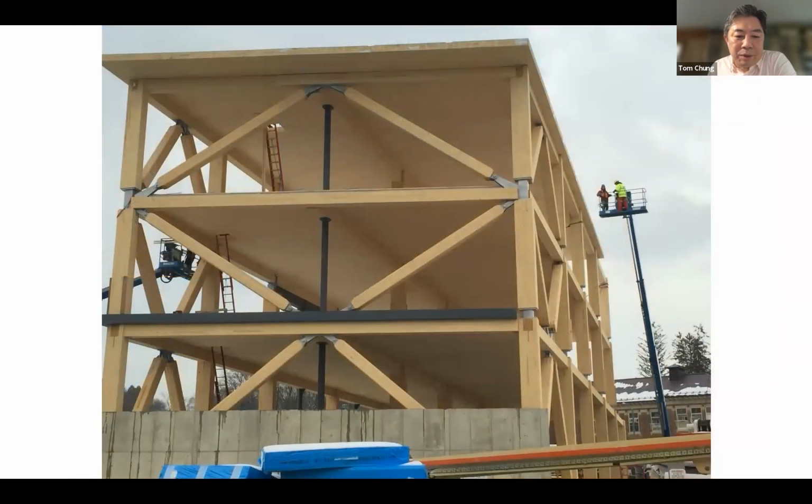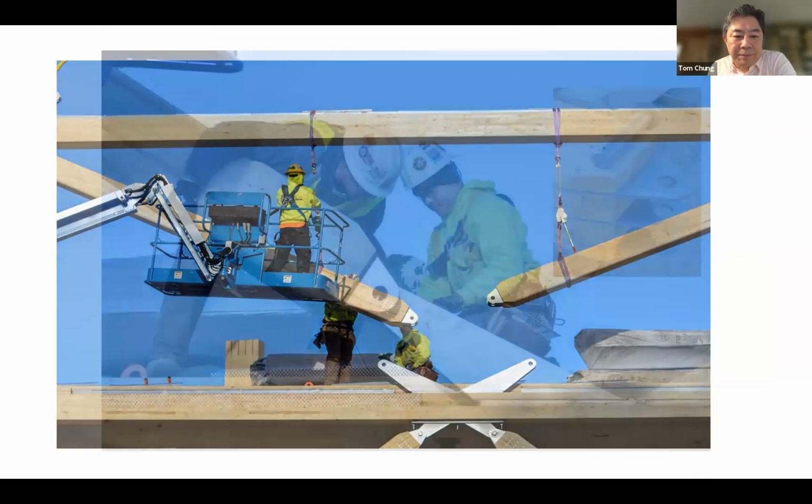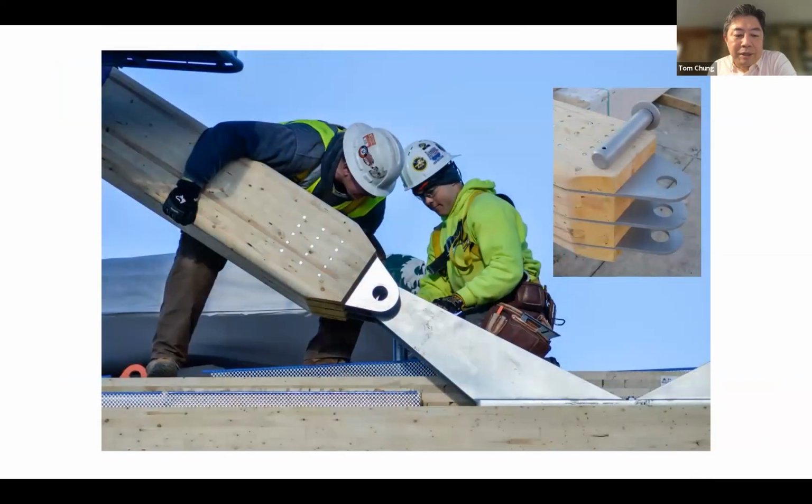Looking at one end of the building where we did not have a core and we had to do bracing for the shear, you can see that installation process as well here. And again, the pre-assembly of all these components results in the field in basically a simple pin joint that goes through 7 different layers of wood and steel. The accuracy and precision needed to make sure those layers between the steel and wood are possible given all of these tiny high strength pins that lock those members into place.